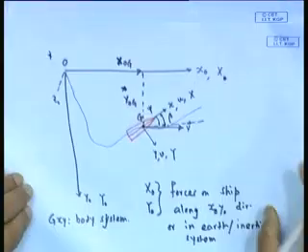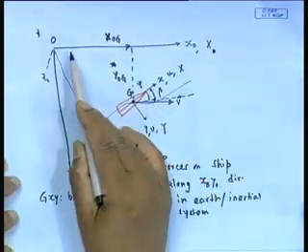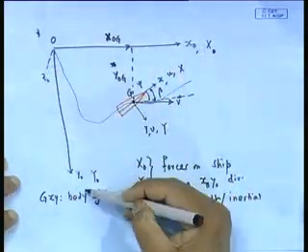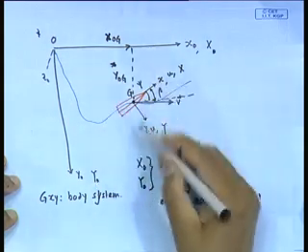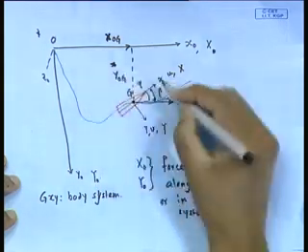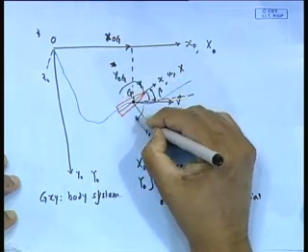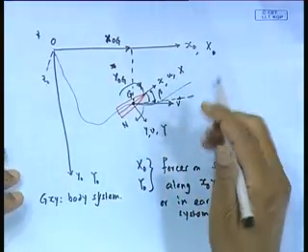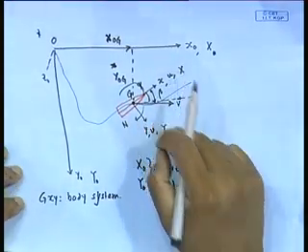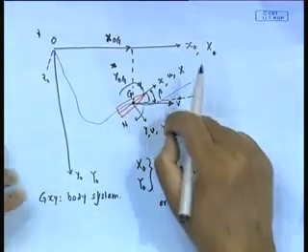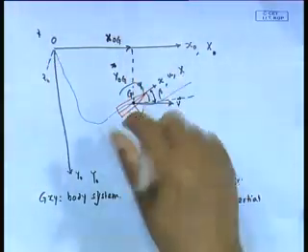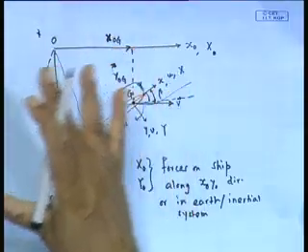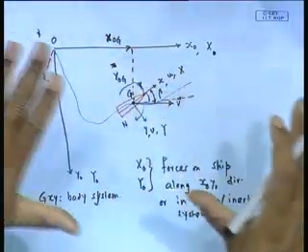Once again, inertial systems are all 0, x0 y0, therefore capital X0 and capital Y0 are forces along this direction. N of course is the moment, which remains the same because in this diagram the body fixed direction z is downward to the paper, that is, going clockwise in a right handed system x to y is downward, which is the same for the inertial system as for the body system.